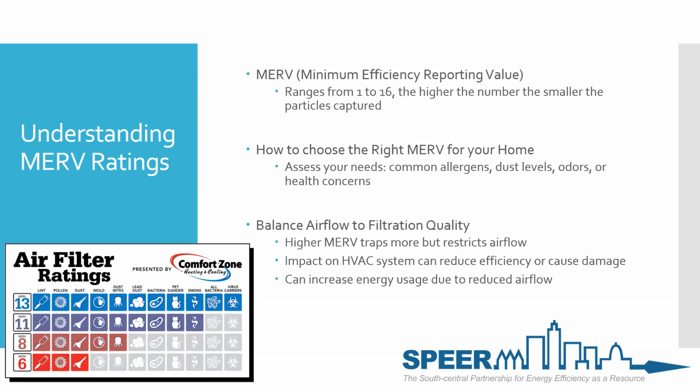Most houses today that I saw, they throw in usually about a MERV 9 or a MERV 10 4-inch media filter. They tell you that it's a 6-month filter and it shouldn't have to be changed more than every 6 months. That's just a rule of thumb. Yours could get dirtier faster, or it could actually last longer. But not knowing when it's clogged up is a big disadvantage to the efficiency of the equipment.